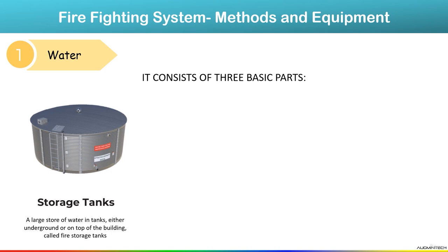These tanks are separate from the tank used to supply water to occupants, which is usually called the domestic water tank. The designer will also try to ensure that the water in the fire tanks does not get stagnant and develop algae, which could clog the pipes and pumps, rendering the system useless in a fire.